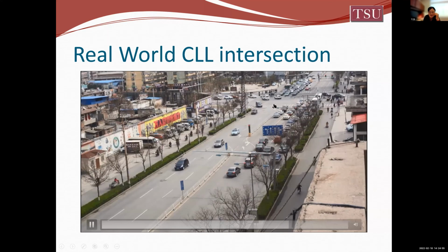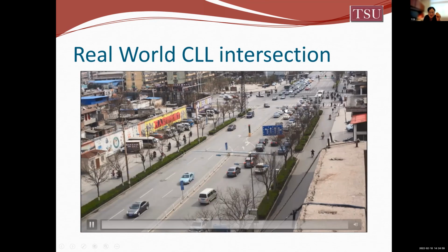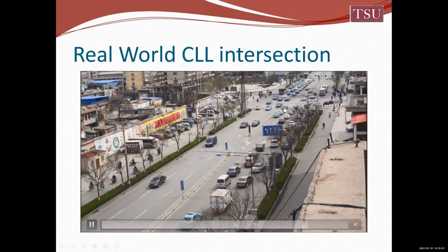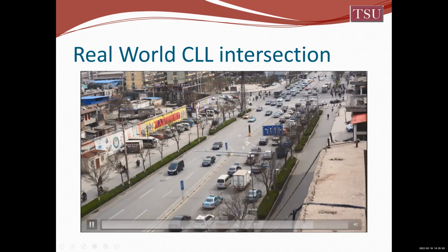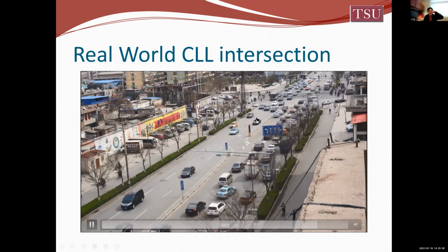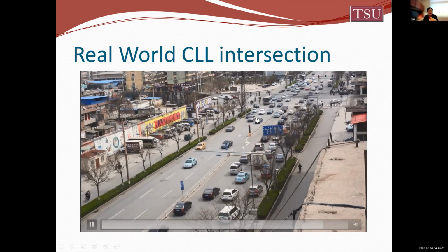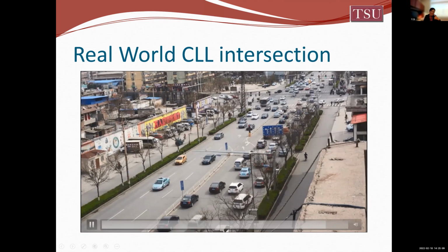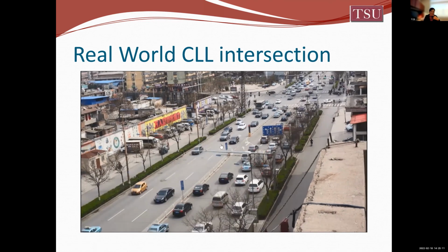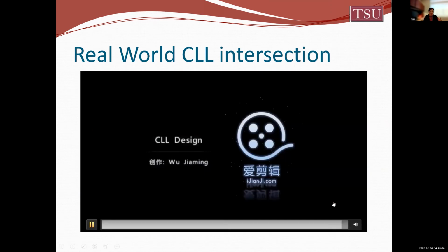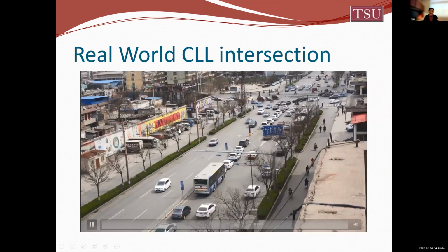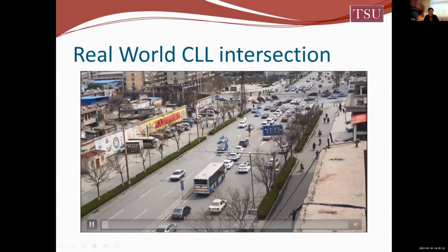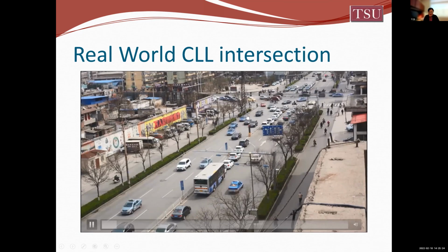Now the opposing traffic starts moving because you already cut the green light. So basically, you can see from this video that conflicts between the right turn and the contraflow left-turn vehicles are very possible. That's why I recommend the channelized right turn. If you want to make sure things work safely, it's better to have a right-turn channel instead of letting right-turning vehicles choose which lane they move into.